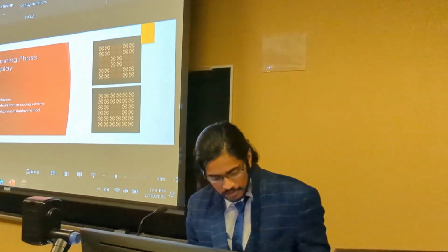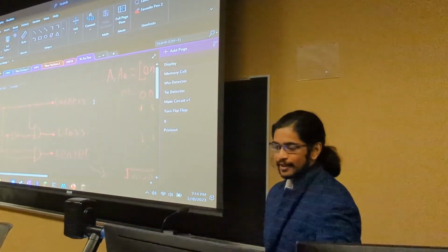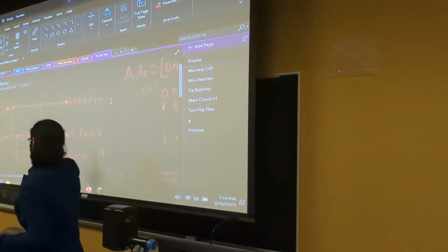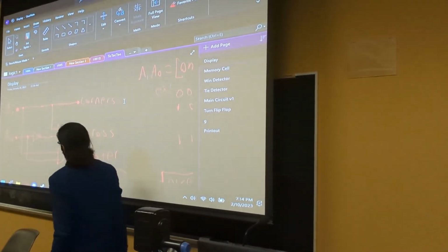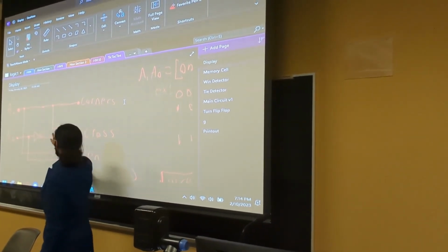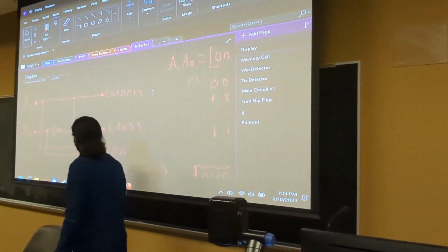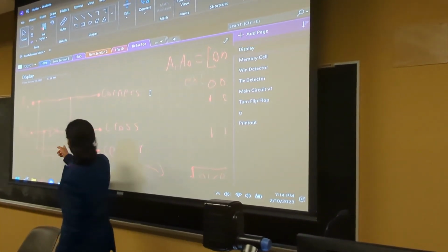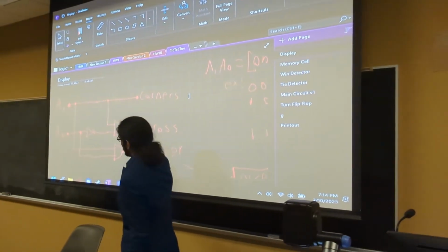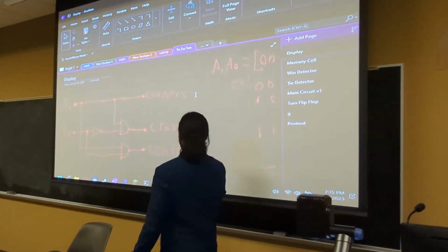And so we can create a pretty simple logic circuit for that as well, where we can have the corners simply tied to the occupied signal, the cross tied to the inverse of the XO signal and the occupied signal. So we don't want to display anything if it's not occupied, right? And then the X turns on the center. We need to make sure that both A1 and A0 are on, because that's how we encoded the X, and send that up to the center.